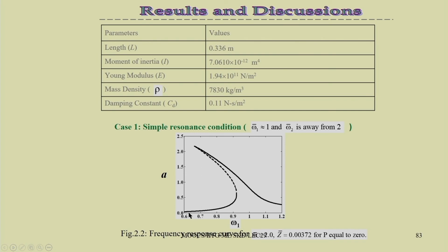If you compare this equation to that of a Duffing equation, you can see it has a softening type of response. Here again we can have the saddle node bifurcation point, at omega 1 around 0.8. If you take around 0.8, it has 2 stable and 1 unstable response. That means the system has a bistable region along with the presence of an unstable fixed point response.